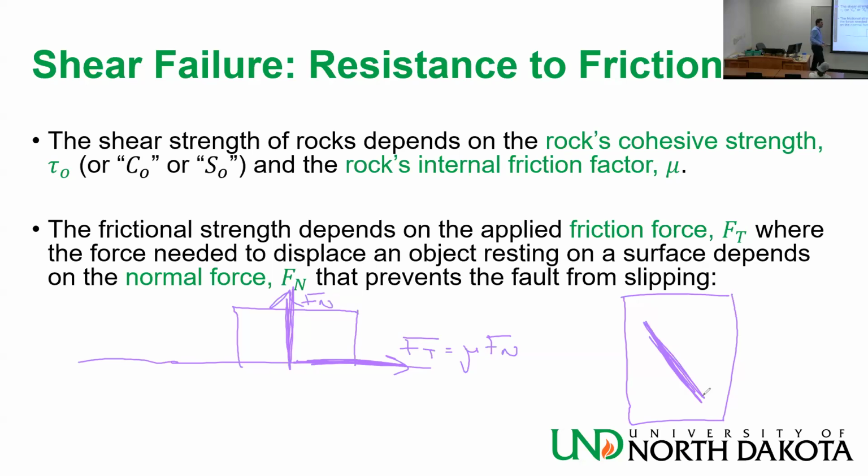We have an infinite amount of faults at infinite orientations and stress at infinite levels. So we can make the assumption which says that if I'm trying to create a fracture in the rock, the best way to make a shear failure in that rock is to have a fault oriented this way, stressed at this level, and probabilistically it exists.